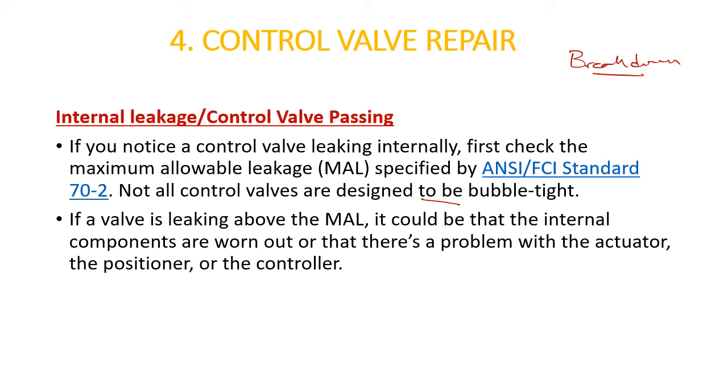Another condition based test is also available nowadays. If there is a control valve, acoustic sensors can be installed downstream to check whether the control valve is passing or not.